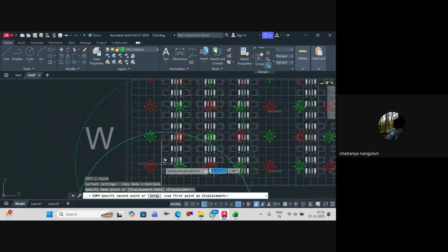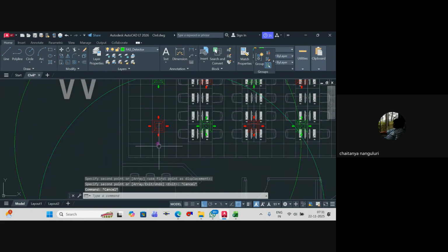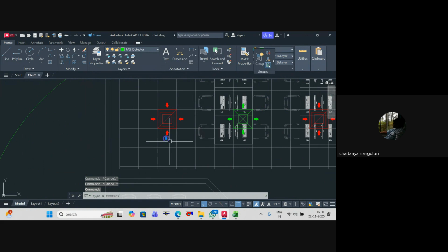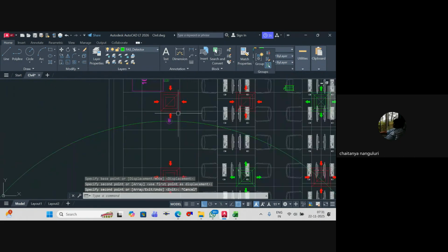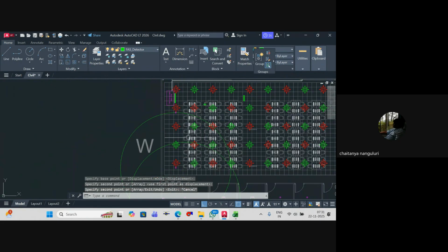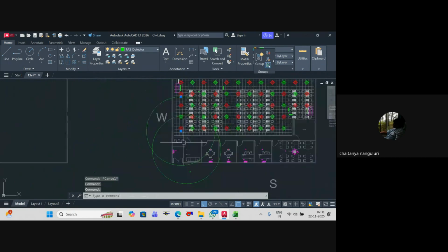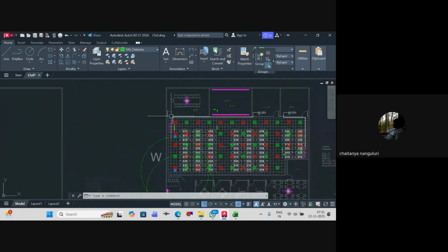So here we'll start. As I've told you, you should have 1 meter as a minimum gap. So let's take it from this corner. Return you can always have; it's only near the supply you shouldn't. The gap between the two should be 7.5 meters. Again, the other clause is confusing. So 7.5 meters means I can have one over here, one detector over here. And then this is definitely lesser than 7.5, so we need not worry.